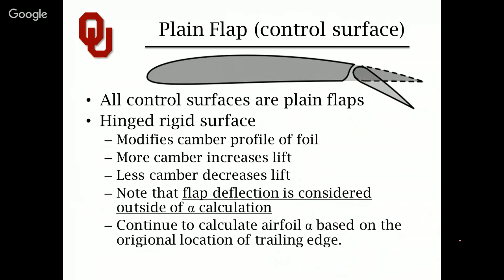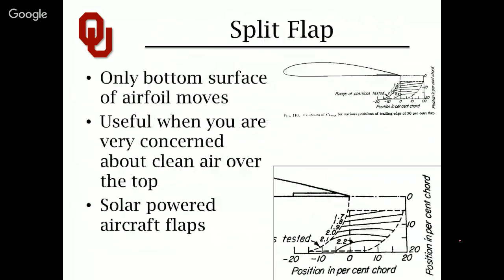One thing that bullet point points out that I did not refer to is that really you are just changing the camber line of an airfoil. You have a discrete kink in the camber line there, in this case about 80% chord, and oftentimes that is controllable. You can have active control of the camber line of a surface. There absolutely are researchers investigating a more organic camber modification system where the whole airfoil will more or less flex, where it would change shape, a morphing control surface instead of a discrete mechanical hinge. That's certainly being looked into and does overall offer some drag benefit.